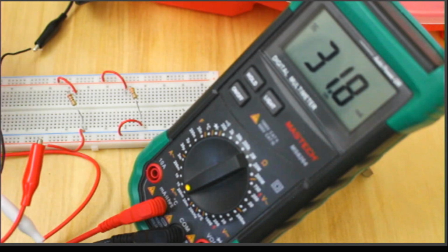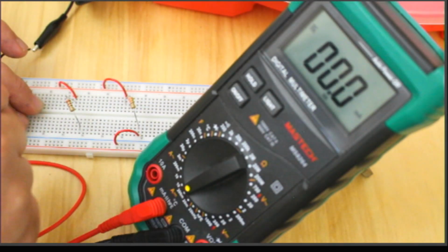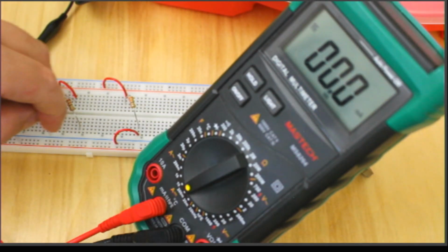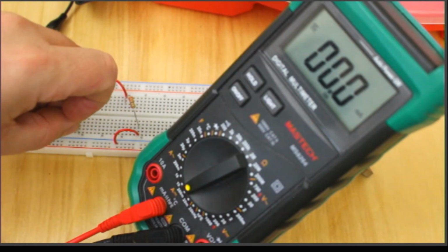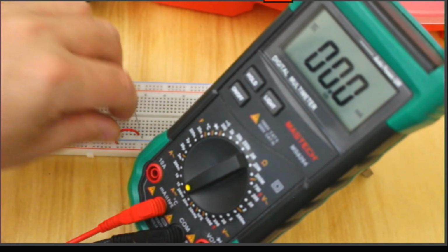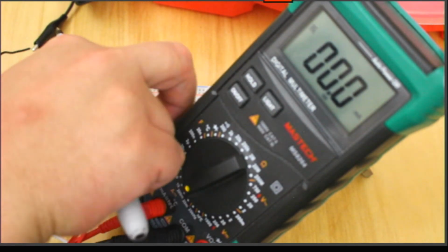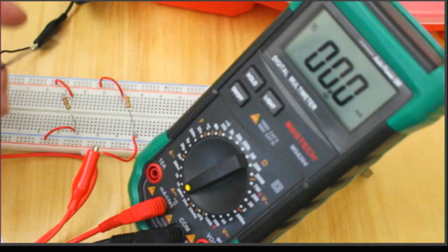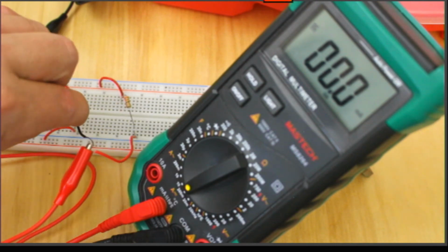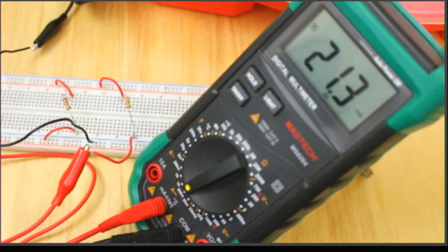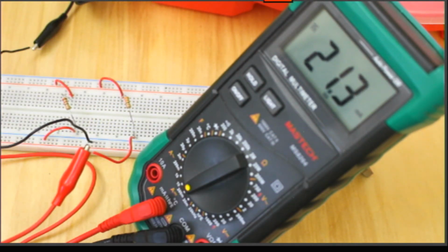Okay, fair enough. Now I take my leads out, I plug this back in, take this one out. Now again, my positive lead touches the same 5 as the resistor, and I put my black lead in the hole in the ground, 21.3 milliamps. Okay, so that adds up actually to like 53.3, so we're within a milliamp here.